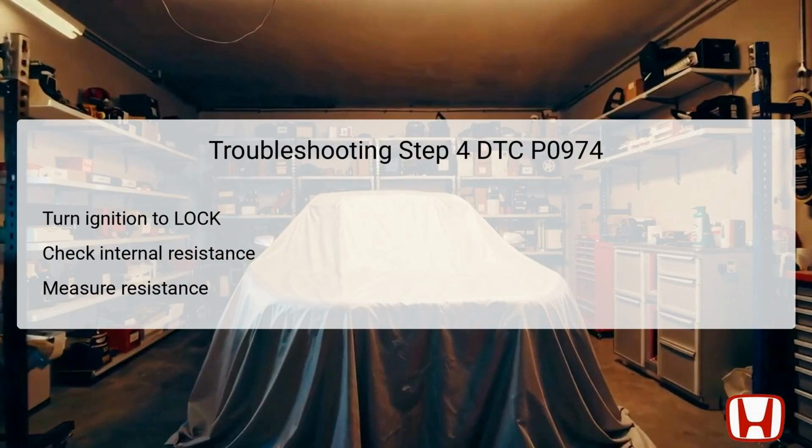With the connector disconnected, measure the resistance between test points 1 and 2 as specified. The appropriate resistance reading should fall between 13.8 to 17.1 ohms. If the resistance falls within this range, it indicates that the Shift Solenoid Valve A is functioning correctly, and you would then update the PCM if it does not have the latest software, or substitute a known good PCM to continue troubleshooting. If the resistance reading is outside this range, this points to a possible fault within the solenoid that requires further investigation.